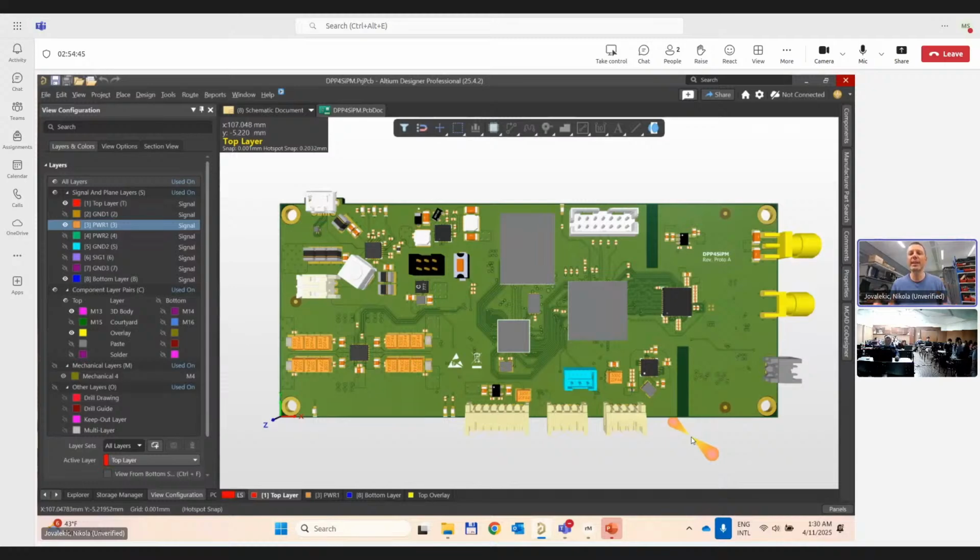So what you observe here is the following. The power supply section, which has a lot of noise, is really apart from the analog part of the design. So they are really spatially decoupled. But that's not enough. But we will not go into details. And in between, we have this digital part. Yes, it needs to be here because you need to connect your ADC to your FPGA. So they need to be next to each other.